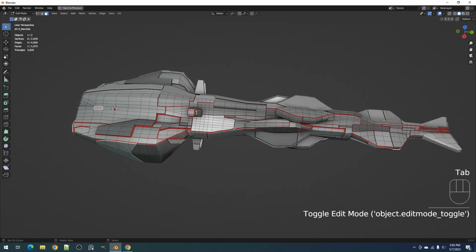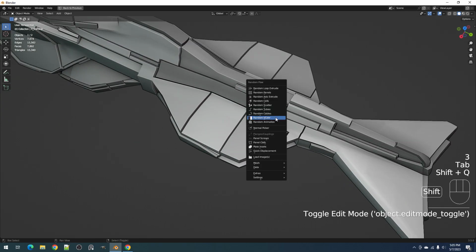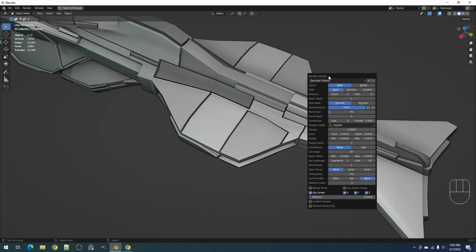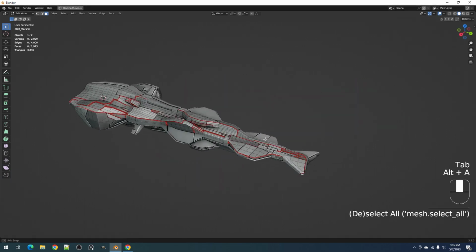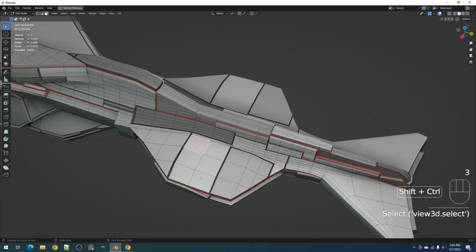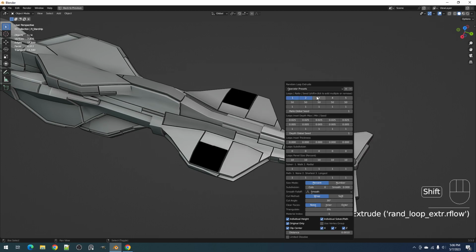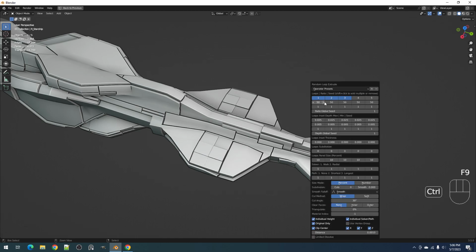So using the random flow add-on, random panels, if you want to use the destructive operators, which maintains the unimesh structure of the ship, unimesh being a whole mesh, and the random flow is mostly designed for non-destructive results, meaning that the result will be separate mesh.